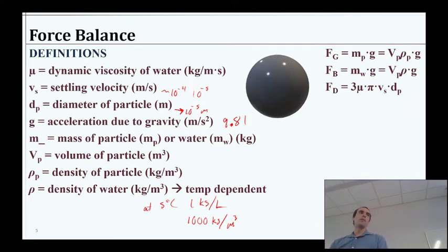And as you'll see in a few minutes, the difference between the density of water and the density of the particles is going to be the driving force for the buoyancy, right? So the bigger the difference, the faster you're going to go, in some sense. That'll be in the relationship we'll derive in a minute. Okay, all that makes sense so far, terminology?